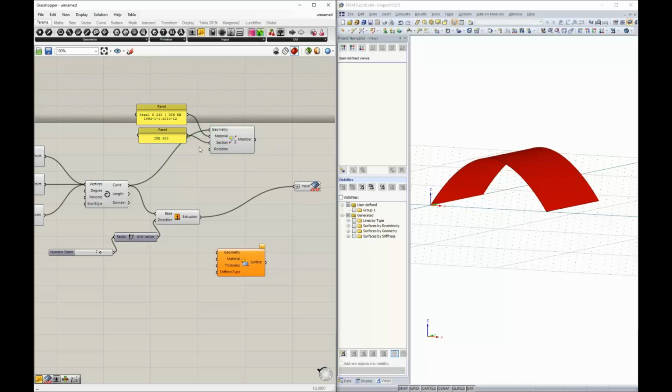Of course, we can change the rotation of a member. We can do it again maybe using a panel. Let's say we enter values from 0 to 90 degree. So here I can switch between the values 0 and 90. I could theoretically connect now this slider with the rotation. There's just a small issue. We expect the rotation in radians. This is degree for me.